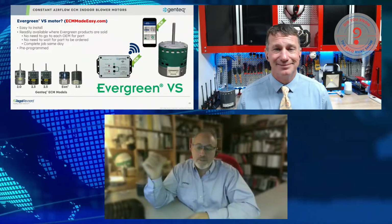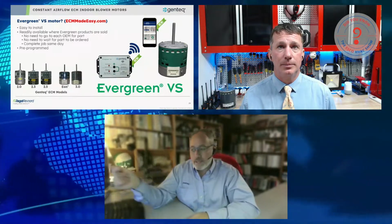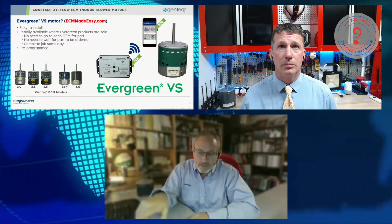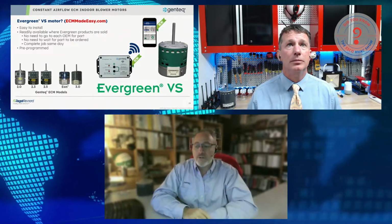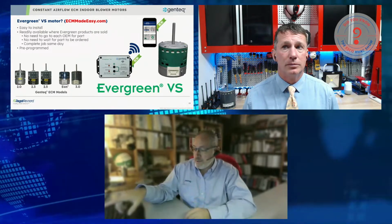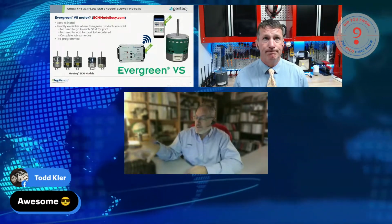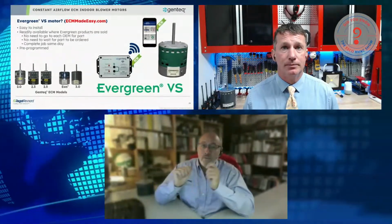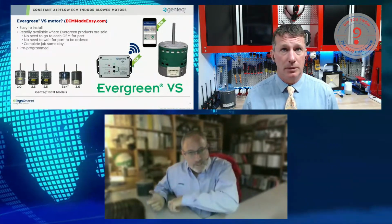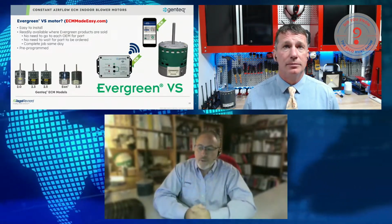So you take the 16-pin plug from the old 2023 Eon motor and you plug it into the side of the user interface, and then the user interface has the 4-pin out that plugs into the new 4-pin motor. We did that because it was easier to do. So you've got the 3.0 with the 4-pin, and you've got all the other motors with the 16-pin. It was easier to replace all of them with a 4-pin motor that we converted over than a 16-pin motor where we went backwards in technology. So we took the most recent technology, going forward, the new model. Everyone's going to be using that.